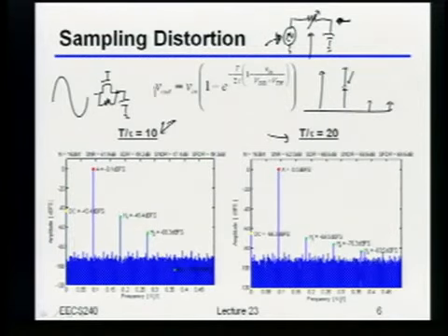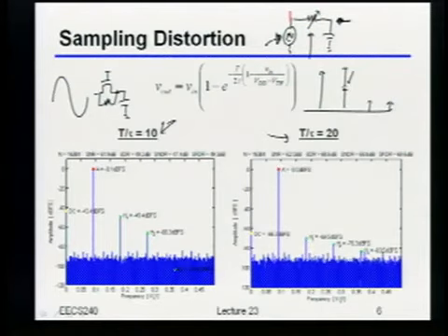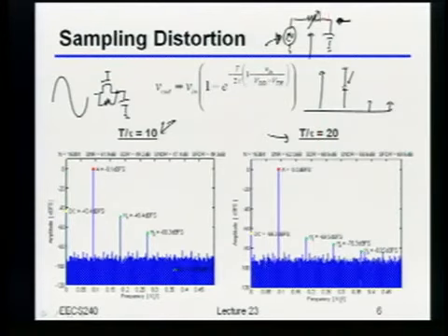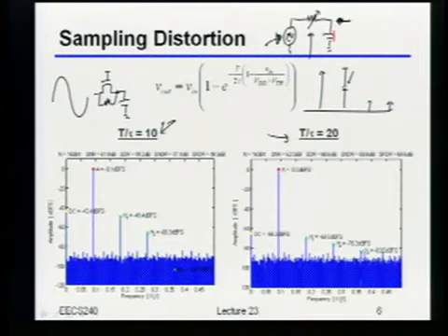So the reason that making the switch faster helps is that even though it's nonlinear and it creates distortion, if you wait long enough for everything to settle, then it better be the case that the output matches the input, right? So by making that switch nominally faster, all you're trying to do is make sure that the output voltage tracks perfectly with the input voltage, even as this resistance is varying, right? In other words, even in the worst case resistance, you're trying to set that tau to be fast enough to track the input sinusoid, okay?